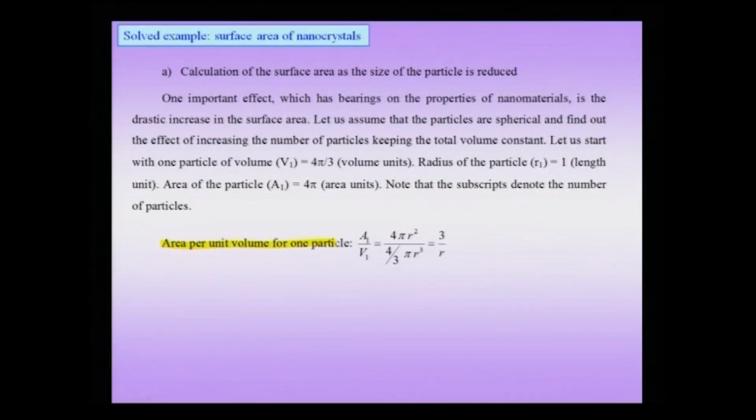And we had noted that suppose instead of talking about only the external surface, we are talking about a polycrystalline material and we are actually reducing the grain size, then the interface area, which is the grain boundary area per unit volume of the material, will increase as I reduce my grain size to very small dimensions. So, let us make a calculation to understand this effect, so that we have in perspective the kind of numbers involved and the effects we are talking about.